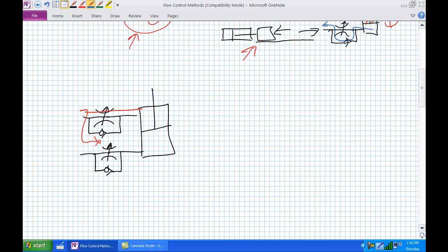But like I said before, this is low pressurized fluid. It's going to push that ball off its seat. It can't support that incredibly large weight. So basically what's going to happen is that piston face is going to slam to the ground because that fluid drains out of the cap end extremely fast.